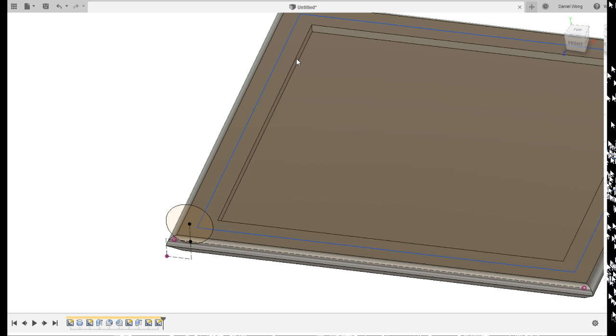I'm not sure if Michael actually went for it or not, but reference geometry is very useful for creating geometry on different sort of areas, right? So I'm going to offset this plane here, and we're going to slide it back 20 millimeters, okay? Like so. And now what I can do is I can right-click and redefine sketch plane.